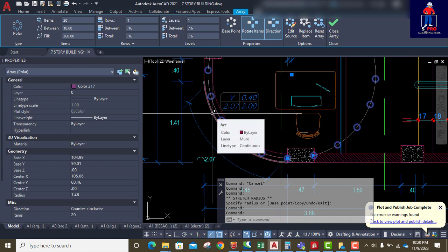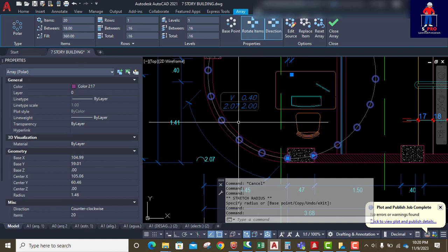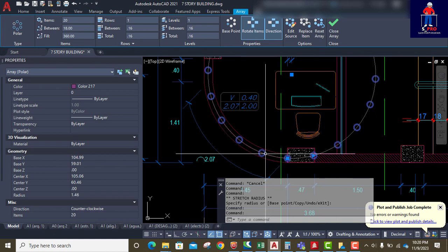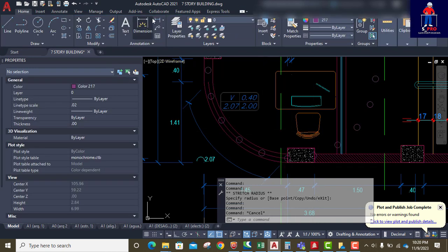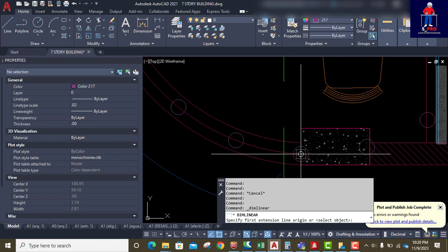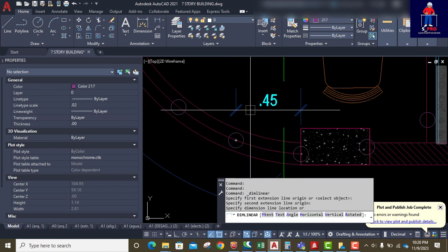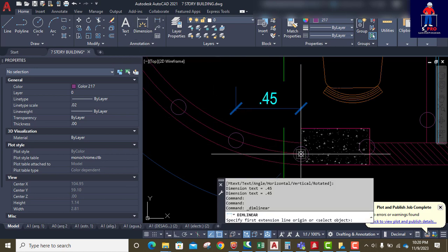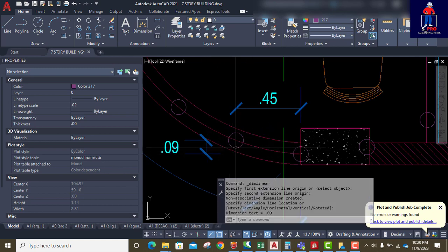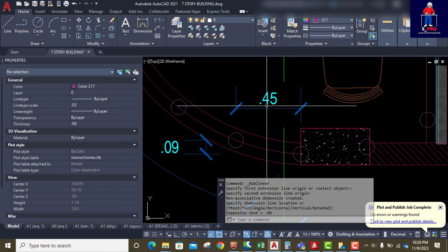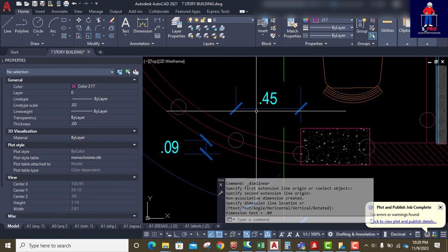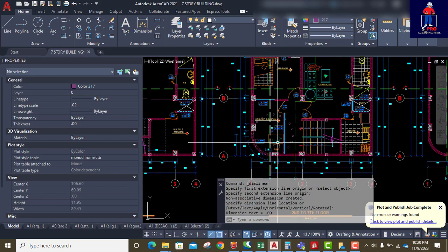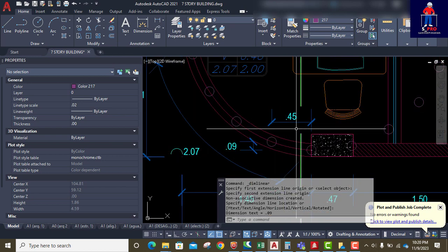It's a normal thing. So if you get few nodes, your arc is not going to be that gentle. It's not going to be that smooth. So what I will do now, I will get the coordinates of this point. So how do I do that? So I'm going to offset this node to this node. This is the x dimension, and I will do for z 0.9. So I'm going to offset with coordinate of 0.45 in x direction. It's supposed to be x. I have my x to be here, my z to be this other side. So it's going to be 0.45 for x, 0.09 for z.